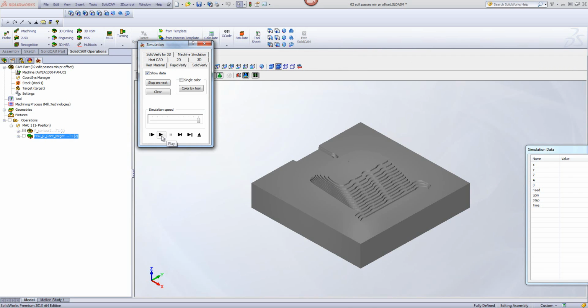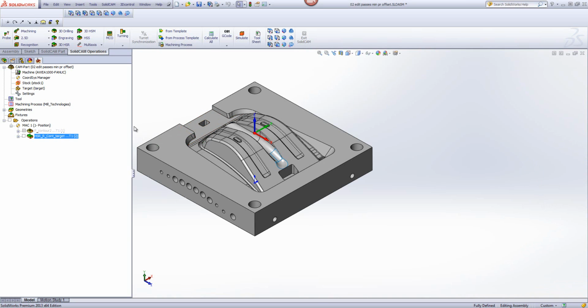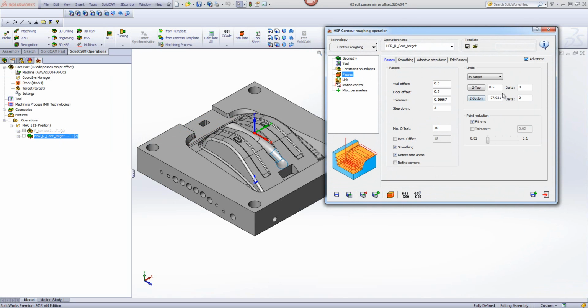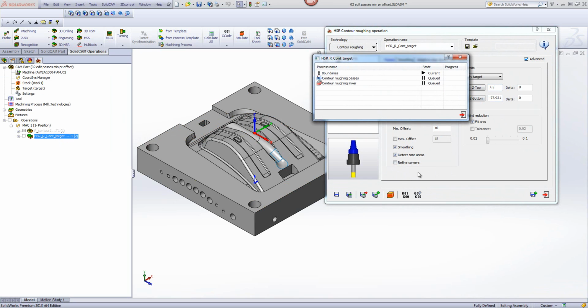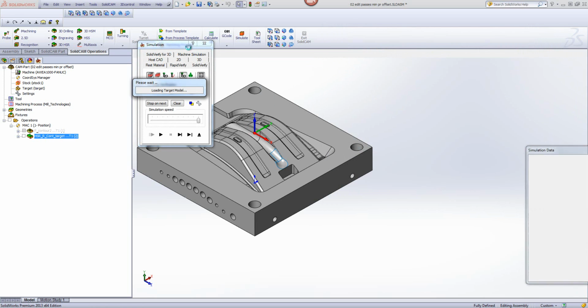And you'll see now that the tool will work exactly. Whoops, my mistake. I forgot to set my passes. I said 7.5 millimeters above the top as well. Now let's do our calculation. And I saw that because of the crash, which is why we have simulation. Now let's run my simulation using Solid Verify.